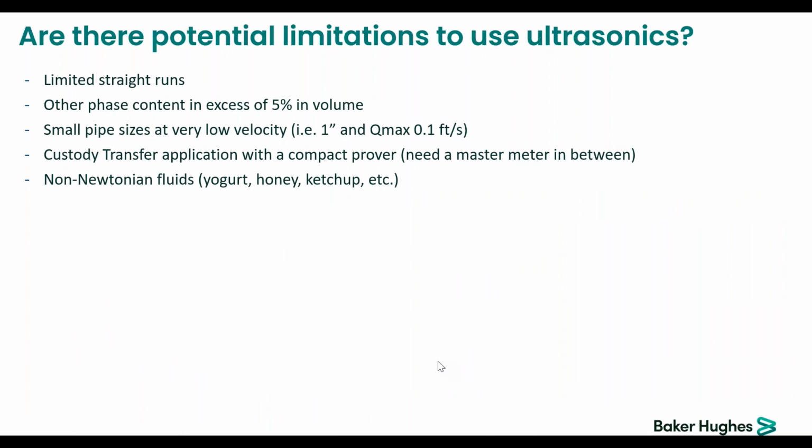So are there limitations using ultrasonics? Yes. You might have limited straight runs, which will add uncertainty to the measurement. You have limitations if you have mixed phases.